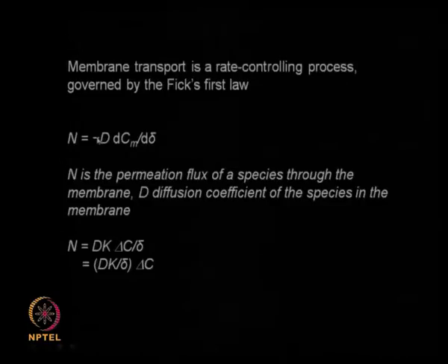Now there is a minus term here because concentration will be going down, the driving force is the concentration gradient, so you are moving the solute from a higher concentration to lower concentration, that is why you have a minus term. So you can little bit simplify it, and then we can put it as delta C here, and this distance between the species can be called a delta. We can bring in the partition coefficient also inside. So we will end up having an equation like the flux is equal to DK by delta into delta C. This is the driving force and this is the property of the membrane.